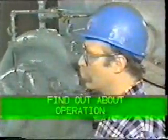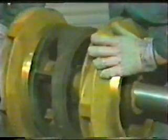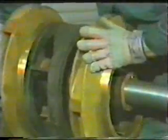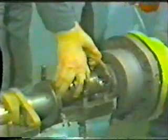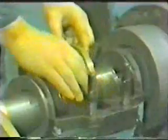It's important to find out about normal operation and to use your own knowledge to help you formulate your question. For instance, Gene knows that the bearings on a centrifugal pump support a rotating shaft. The shaft must be properly aligned in order for the bearings to perform without problems. Of course, a correctly aligned shaft will maintain all components, such as the impeller, wearing rings, and bearings in their proper relationship. On the other hand, misalignment can cause component problems, such as causing the bearings to overheat.